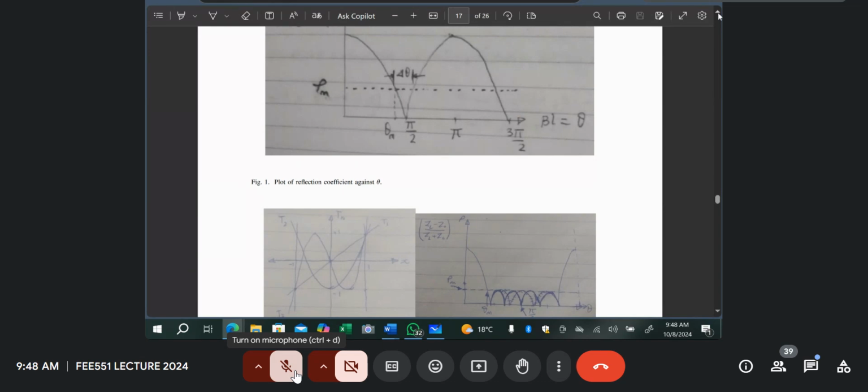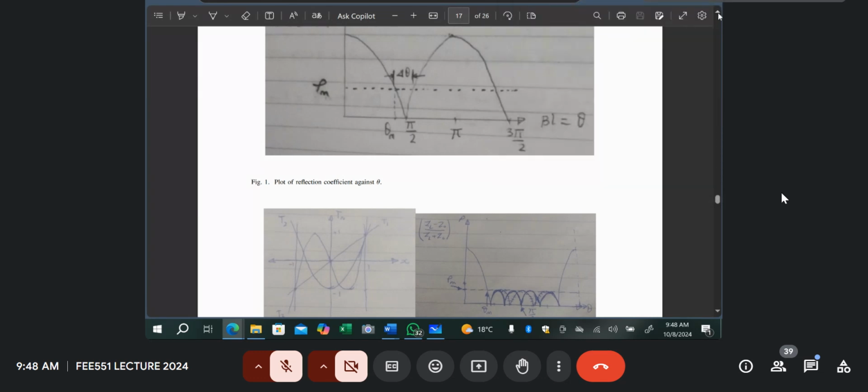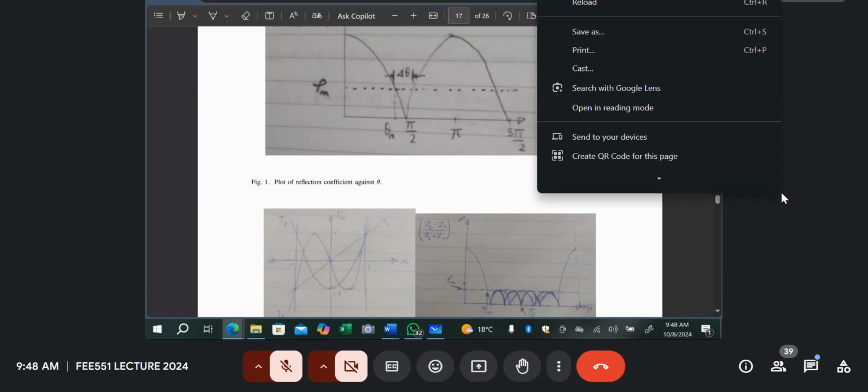So that is good for us. When we use a Chebyshev transformer, because it has this ripple effect, it is going to cut off the peaks of the reflection coefficient, isn't it? And that's our desire. We want minimum reflection, isn't it? So the Chebyshev transformer is able to give us these lower peaks of the reflection coefficient for a wider bandwidth. So it means it's opening up our communication system. The same network we can use under a wider bandwidth of frequencies. So that's a good thing. Unless you're asking something else.